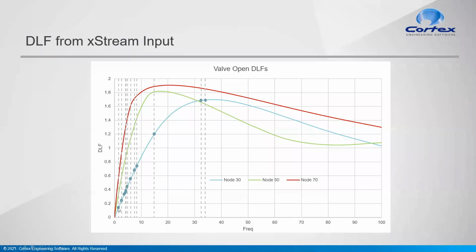So the first mode of vibration for the piping system has a dynamic load factor of less than 0.2, which is significantly less than 2, obviously. And as we go into each of these different natural frequencies, in this particular case, we get increasing dynamic load factors as we go up through the various modes.